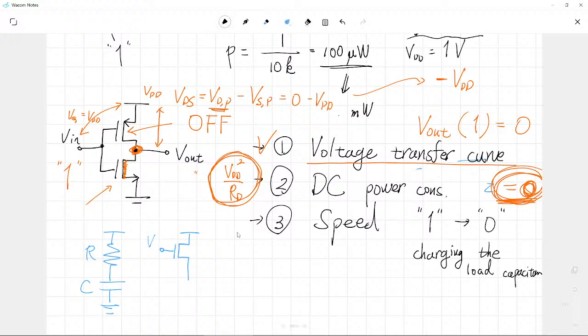In this case, our PMOS is biased with 0 bias for our gate voltage. Its source is tied to VDD, and its gate voltage is 0. Then what is the voltage difference between these two? Yes, once again, VGS of our PMOS transistor is simply given by minus VDD, and this is the best condition for current conduction. And how about the initial value?